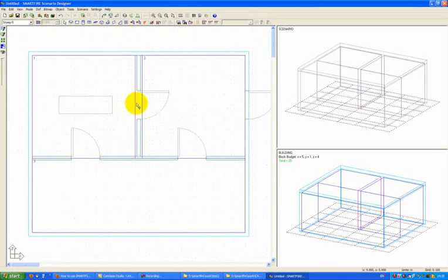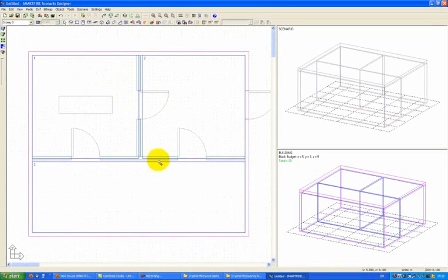Again, you can see here that there is some interpretation needed, because that is one valid solution, that is another valid solution, and that is a third valid solution, based on the accuracy that I've prescribed for the Snap to grid. I will choose to move to there, and similarly on the bottom edge to there. We now have 3 room compartments which are completely separate.